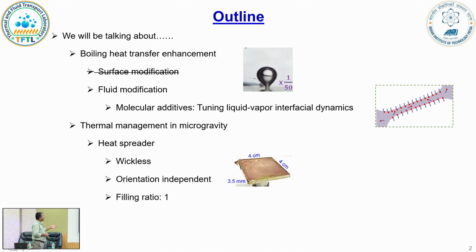And having done that, I will show you how we can use some of this output from the interfacial science to devise something like a heat spreader, and that will go in very well with the topic that has concluded. Okay, so it's kind of a vapor chamber, but something totally different, and it's wickless. It can work on completely orientation independent conditions, so any orientation gives the same results, and it's completely filled. So it's not relying on liquid to vapor phase.